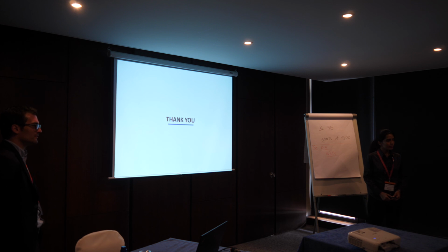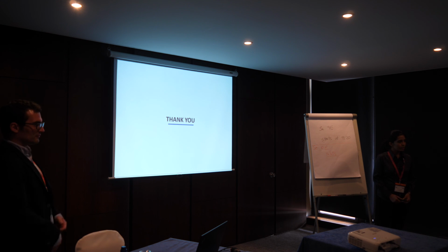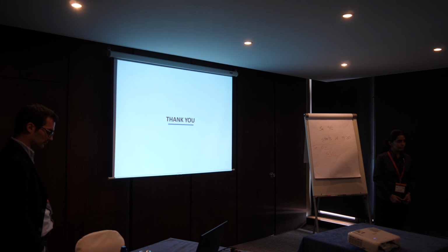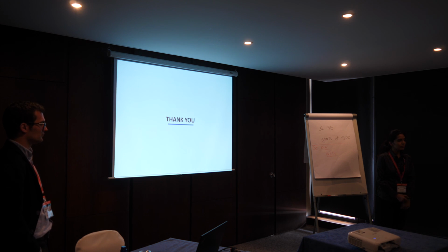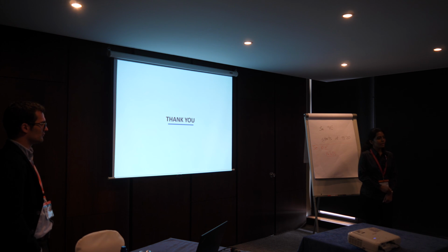What you're simulating is not an iterative approach, right? You first compute the temperature field, and then you compute the stress field. Because of that, I would expect that the dislocation might start moving, and that would again have an effect on the temperature field and the stress field. But you're not doing this, you're doing a one-time forward simulation. Is that important or not?